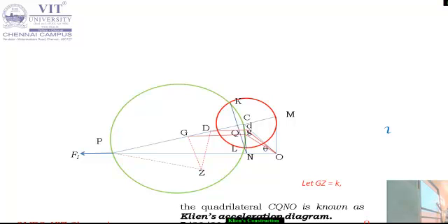So parallel to this OD, you have to draw one line from D till the line of stroke. You have to extend up to this. So this point may be taken as E. Then the resultant force, because the force will be concentrated on the center of gravity point G, always the resultant force which will be acting through E should be parallel to OG. So from E you have to draw one line, you have to extend. That is the inertia force of the connecting rod, which is acting parallel to OG.